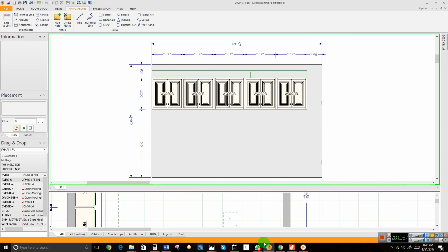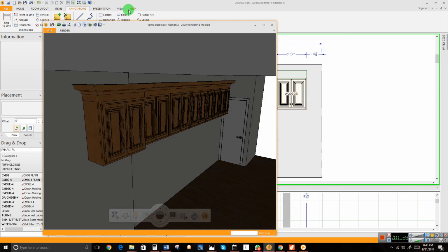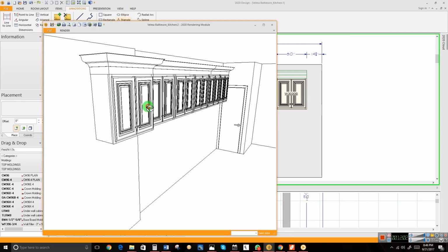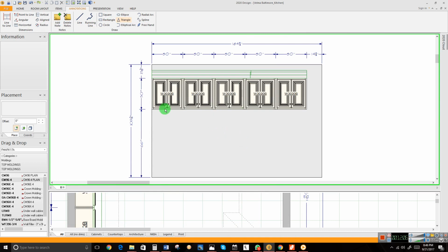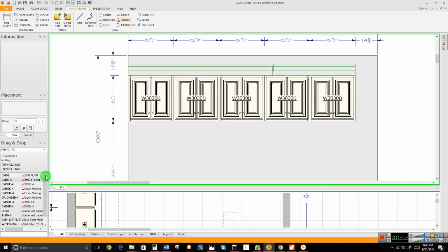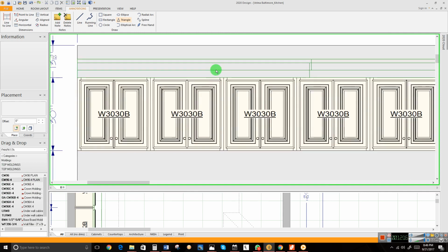And in conclusion, you want to take a look at this briefly. That's done. So we did 2 things today. To drop a crown molding on any cabinet above, all you need to do is go to the elevation. That is the best way. You drag and drop on the elevation. Never drop above what you want to do. Always drop close to the upper face of this cabinet or the other one. Now once you do that, it spreads itself automatically. It spreads all around. That's 2020 for you.